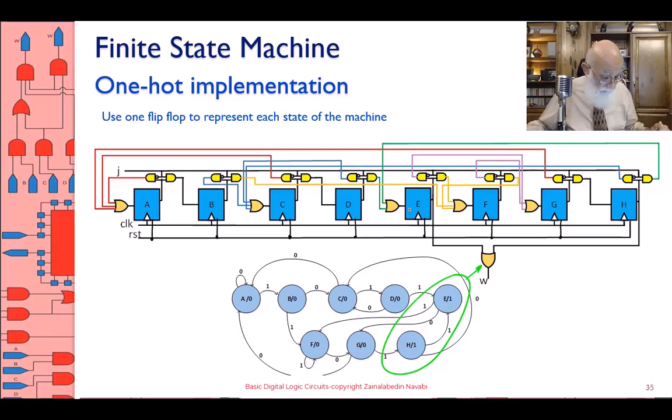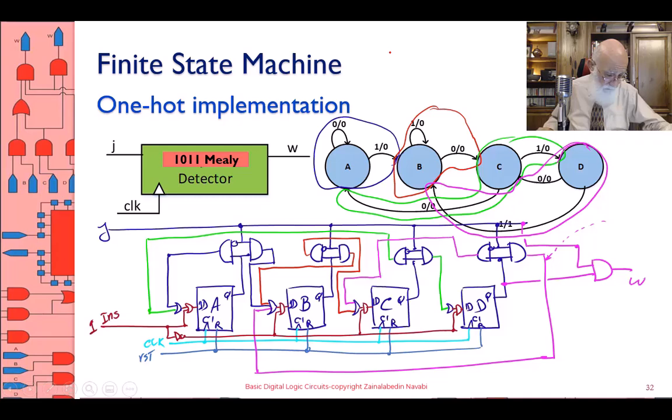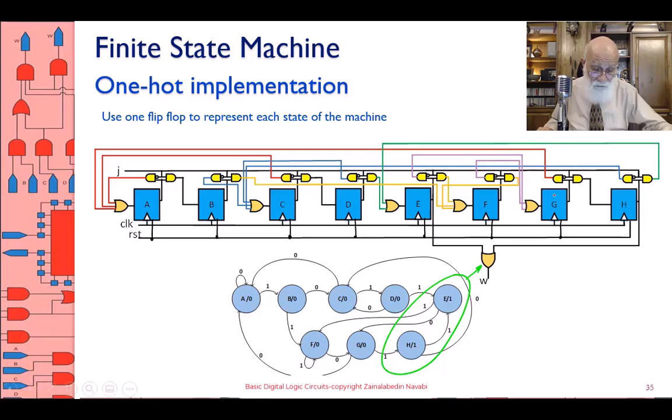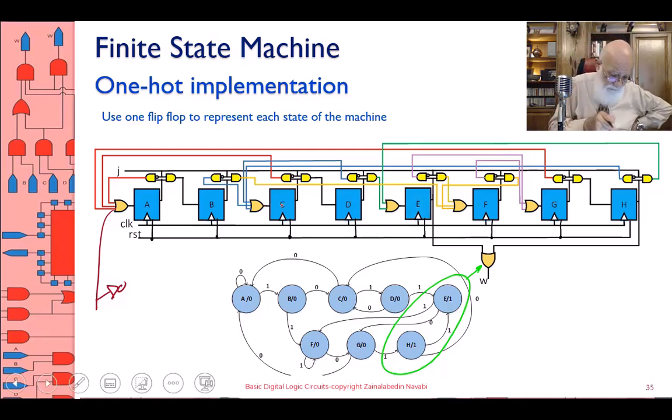The other issue that we dealt with in the previous one, we haven't shown it here, which I'm not going to do. That was the initialization, which we did with this dark red. For this one, I need to put it into an OR gate. There is already an OR gate, so let's keep it there. And then I complement this, put AND gates, put AND gates, put AND gates. Okay, I don't want to ruin the circuit, but then you put AND gates for 1, 2, 3, 4, 5, 6, 7.